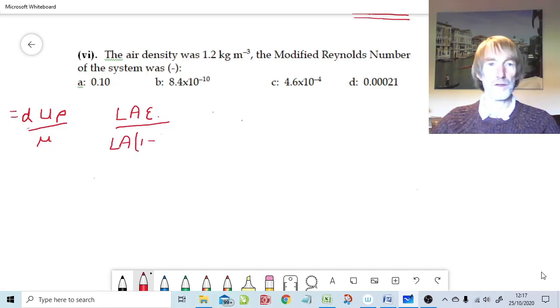So it's the solid's surface area, because that is now the volume of the bed times the solid's concentration. So that's the solid's concentration. That's now the solid's volume inside the bed. That would be meters cubed of solids. And if we multiply that by specific surface, that gives us the surface area. That now is in meters squared surface area of the solids. So that is our equivalent hydraulic diameter. It's the volume of voids open to flow divided by the surface area of the solids.